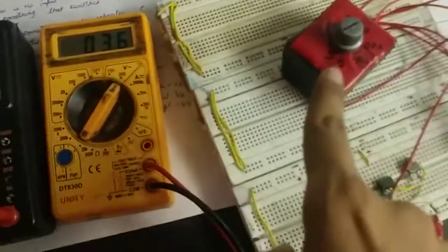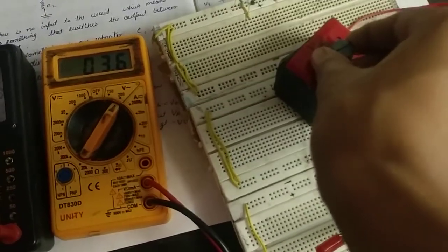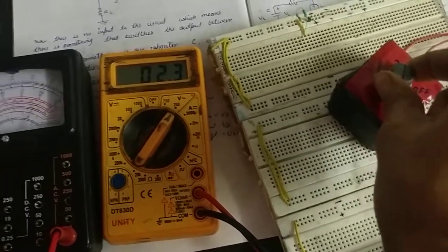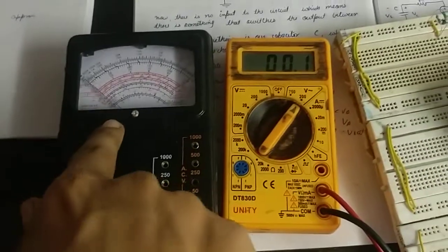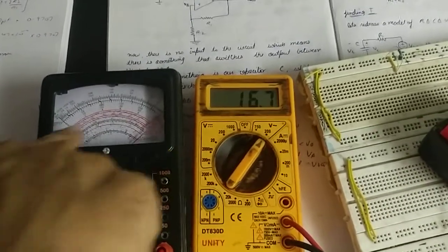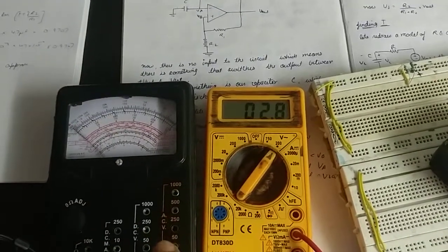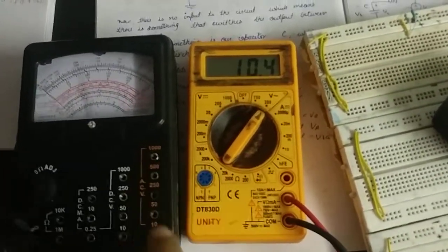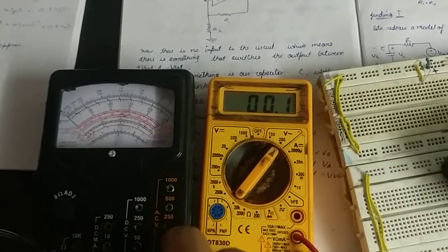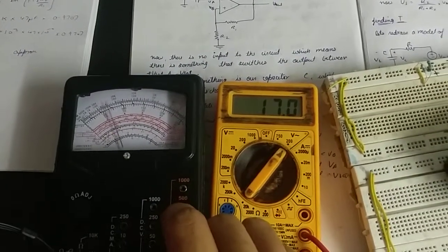So now this is the range selector, with which I can select the capacitor and connect it to the main circuit. Currently it is at 10 nanofarad. Now let's move it to 47 microfarad. Now as you can see, the meter is actually oscillating. It is hitting the rightmost part of the multimeter, because I have set it to the 10 volt range of the AC signal, and since it is at the 10 volt range, it is maxing out the top value.